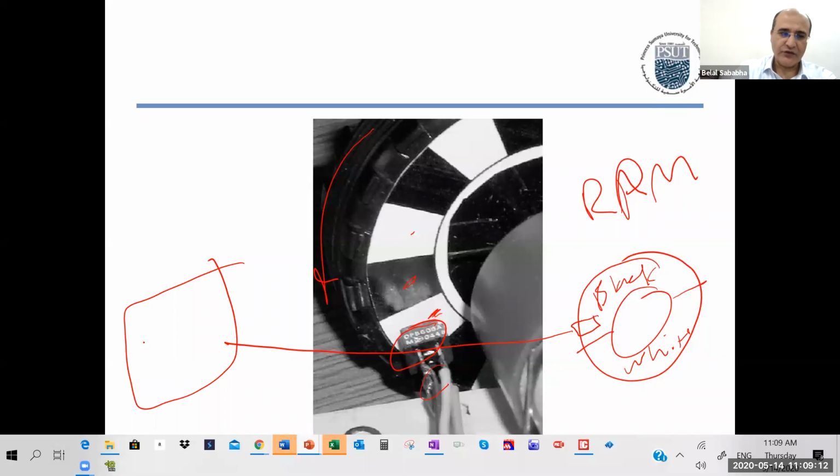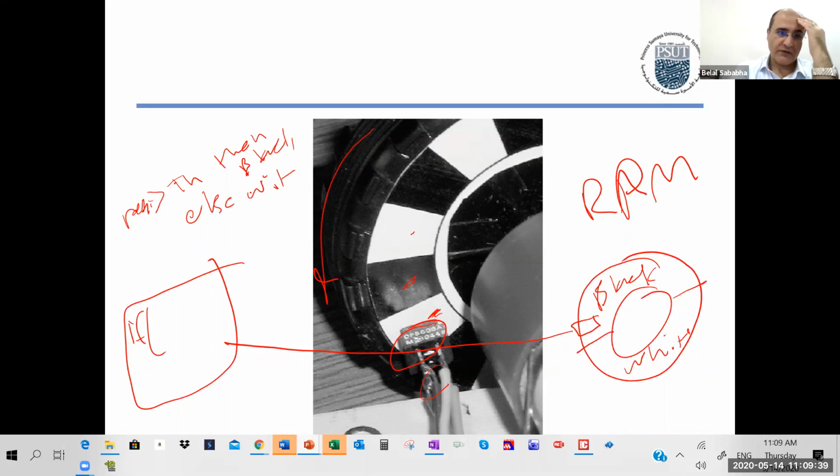So you say in your code, if the reading of the sensor was above the threshold, then black, else white. You can put this in an interrupt and do it every millisecond or whatever.